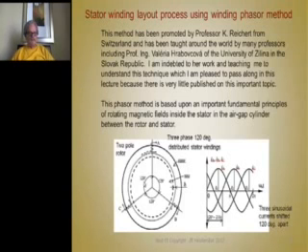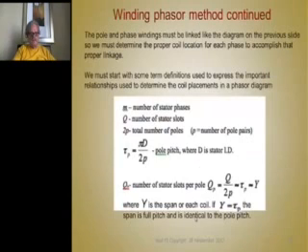So this example here is a 2-pole rotor, and there's 3 sinusoidal distributed windings in this stator, and they have to be physically located 120 degrees apart. And here we see a plot of the 3 sinusoidal currents 120 degrees apart that the inverter's got to supply to this machine, and the rotor will see these 3 sinusoidal currents and linked with the rotor flux, providing that we've got the coils placed in a balanced fashion 120 degrees apart. So given any number of coils, we got to figure out how to do that.